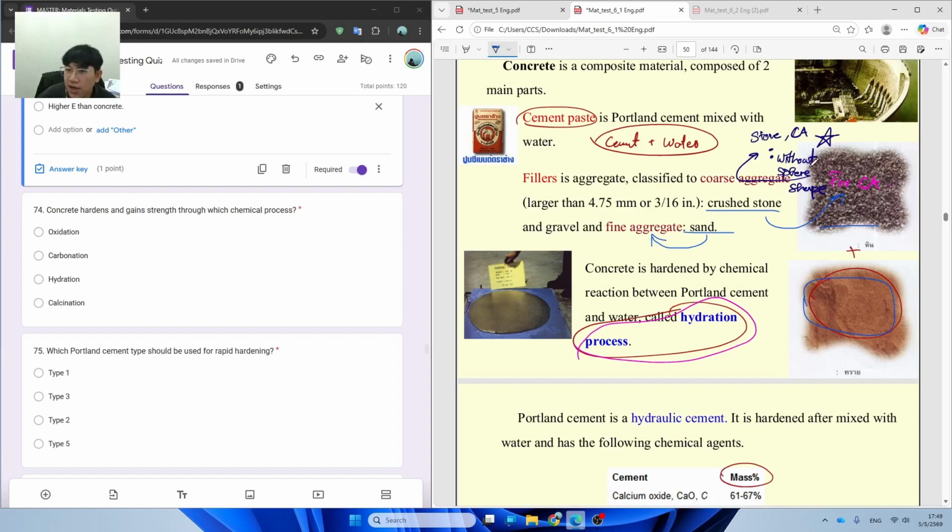A good coarse aggregate is supposed to have a granular, angular shape, not a spherical or rounded shape. The granular shape of the coarse aggregate is going to provide really good adhesion, or really good interlocking, between mortar and coarse aggregate. So if you mix it or buy the coarse aggregate, you need to observe the shape of it too.